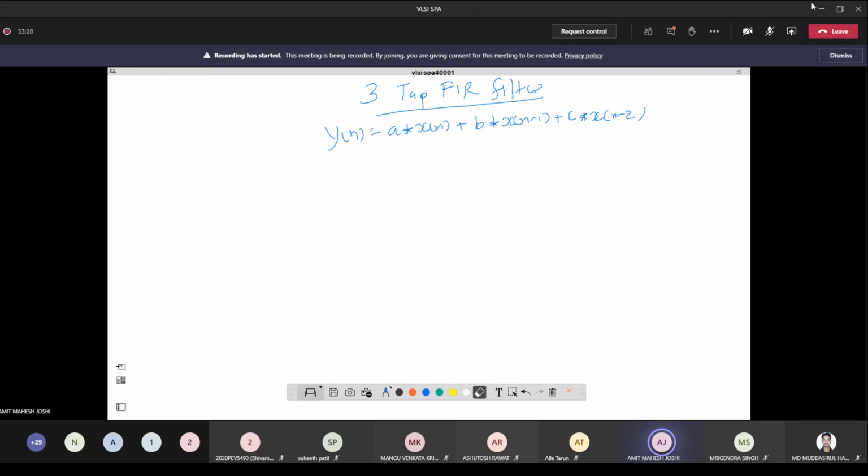Now, I want to understand the retiming concept with this 3-tap FIR filter. Okay, which you can consider the simplest DSP circuit that you have. So when I understand this, then ultimately I have a Xn. That Xn is being multiplied with the multiplier where I apply A. Then it will generate A into Xn. Okay.